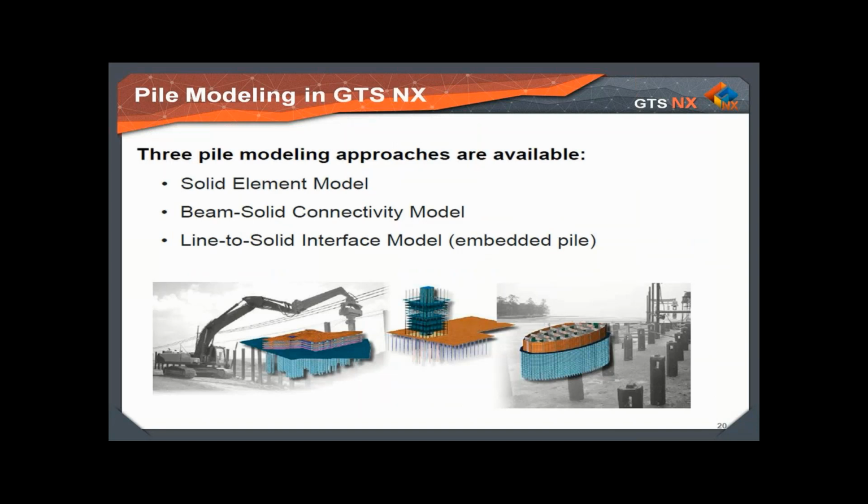When we come to GTS NX, we can model piles with three different approaches. In general, in a 3D numerical tool, you should be able to model your piles as a volume element, and you should have a proper interface around it to capture the interaction between the pile and the soil properly. This is a basic ingredient you should have. In GTS NX, we can do that. We can model the pile as a full volume element, a solid element model with an interface around.